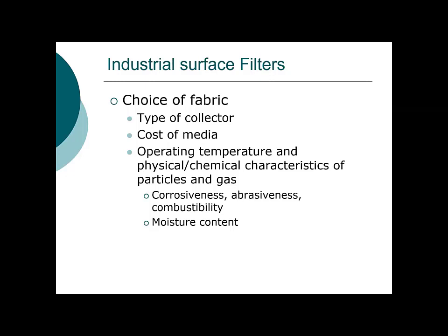And there's some play in terms of the temperature. You can operate at lower temperatures, but then you have the potential for condensation on your fabric, and that can result in corrosion of that fabric material. And deterioration results in potential holes in the fabric, which means that they don't work very well.